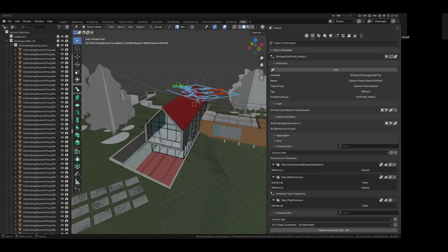Yeah, so I guess for people who don't know, in IFC there used to be, for some objects such as walls and slabs, another type of classification. There was an additional type of classification known as IFC wall standard case, or IFC slab standard case. Basically the same thing with the words standard case written after it.